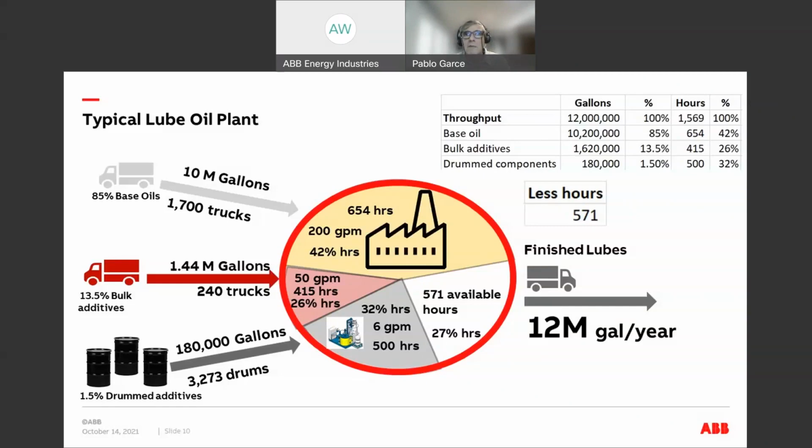You can even move a 20,000 centistokes component, very viscous. We're talking about something like cold honey that barely moves. The machine can still decant a full drum in 9 minutes. With any other system, it would take you between 45 minutes and an hour to decant it.